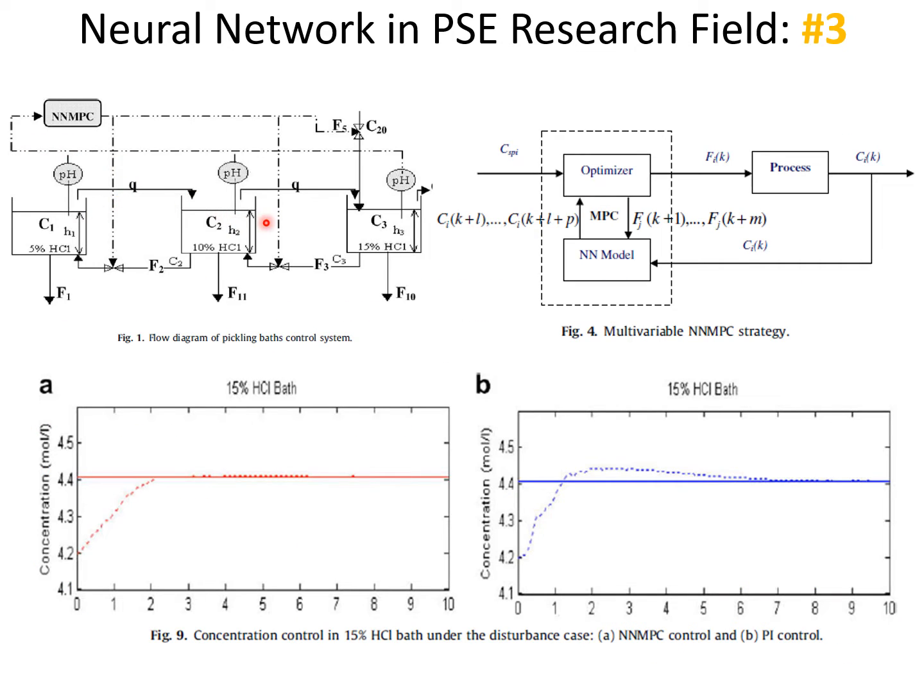And again, this is a steel pickling plant. In the different tanks, we have different HCl concentration. We have to control the pH in each of them, and at the end of the day, we would like the concentration to be whatever we have fixed for it. Okay, in the 15%, the final one, and the others as well. In this case, we implement on 15%.